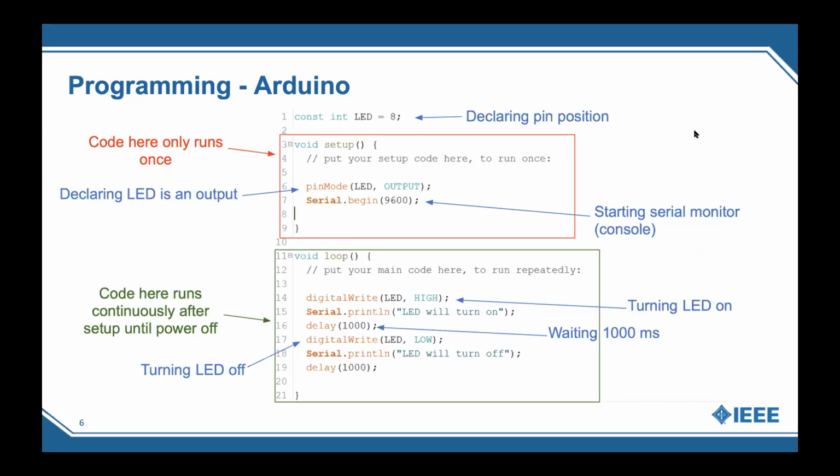And then always in void setup, you have Serial.begin and then 9600. It's for the serial monitor. Basically, it's for the processor to know the speed to run the program. And then over here you have the void loop, which would be similar to the integer main or void main in C programming. This is where you put the body of your program.